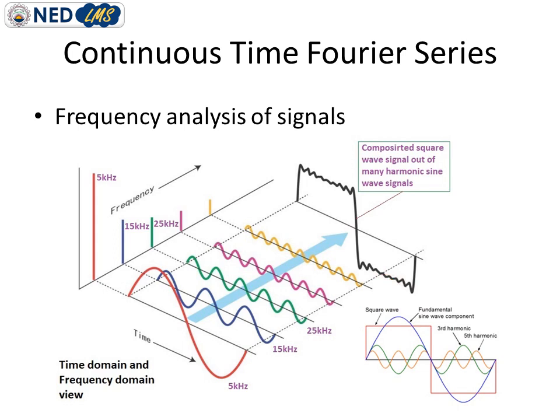However, this is not a perfect square wave, which Fourier also claims: for a perfect shape you may need an infinite sum of sinusoidal components. But here we are adding up a few components, that's why we are getting the approximate shape of a square wave.